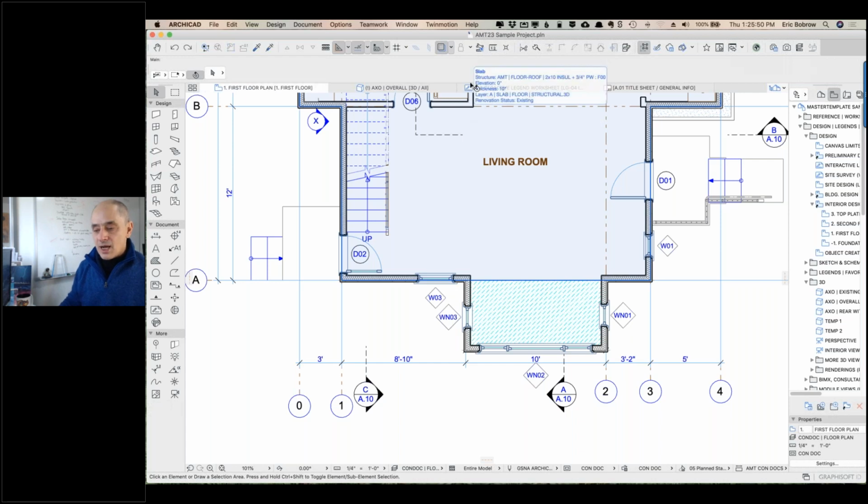So guides, just in general, if we go to tips and tricks for newer users, guides are shown or hidden based on this control here. So guidelines you can turn on or off. Let's just drag a guideline in to a location like this. If I click here, I can turn them off, click again, turn it back on. So it's still there, but it just gets hidden.